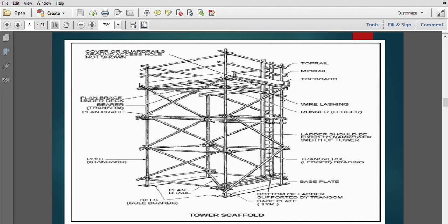I'm showing you this is the post. Okay, this is the post, 1, 2, 3, 4 posts. So, for example, you have a joint somewhere here. If you have a joint in this area, it is rejected, or in this area, it is rejected as a major fault. You are allowed to have a joint from this area to your cross section area.